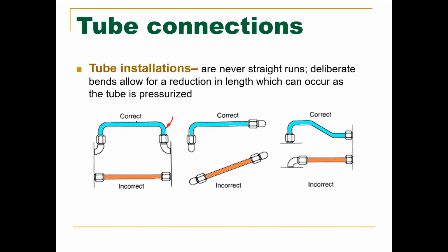All right. Also, when the tube pressurizes, you could be sitting in port and these will break just because you pressurize the system. All right. So always think about what's going on, all of the forces that are happening. It's not just what's happening inside the system, but outside forces as well. This could be attached to a bulkhead, not just an entire piece of equipment, with another piece of tubing on the other side continuing out. So it could be rigidly connected.